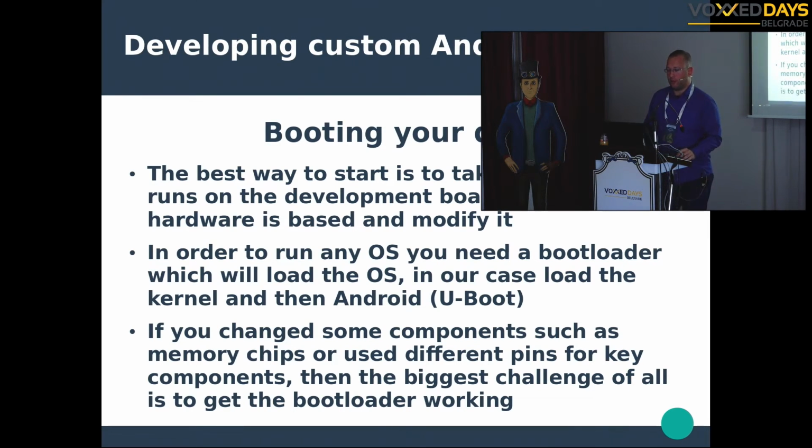So you need to have a bootloader, and in our case, for Android and especially for the IMX platform, the bootloader is called U-Boot, and it's one of the popular bootloaders, developed by open source. So you have a lot of resources, mailing lists, where you can ask questions if you are stuck, if you cannot make it work.